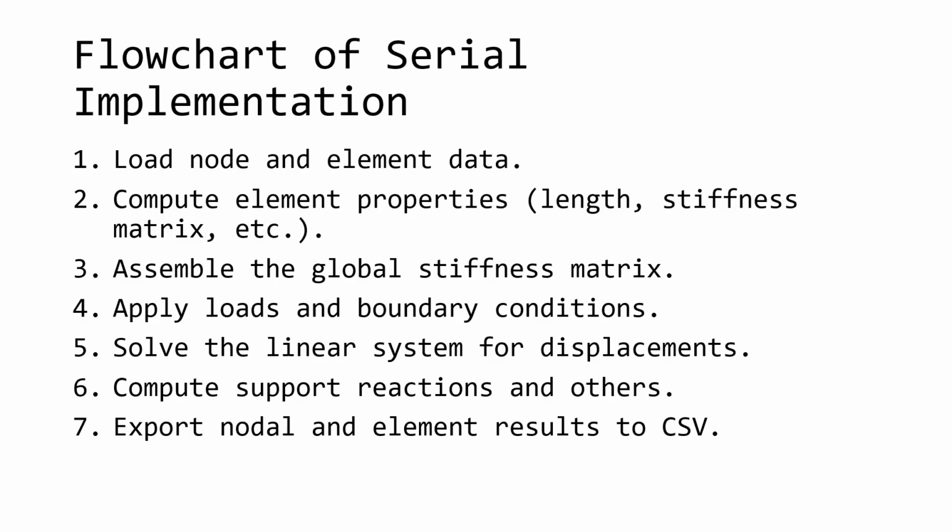This flowchart summarizes the overall process. 1. Load nodes and element data. 2. Compute element properties. 3. Assemble the global stiffness matrix. 4. Apply loads and boundary conditions. 5. Solve the system and get displacements. 6. Compute reactions and others. 7. Export all results to CSV files.